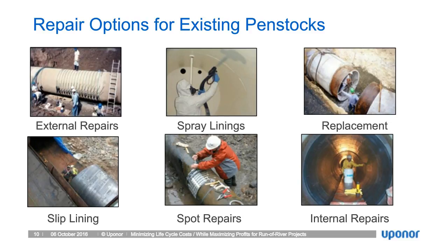Spray linings: sometimes if it's a steel pipe and you're just looking to reduce corrosion potential, or some of the linings have a better Manning's number, they're slippier. Linings such as epoxy or urethane can be applied to the surface to help extend the life expectancy of the materials, as well as increase flow velocities because the liners typically have less resistance. The con with liners is that they are liners and they do wear out. If you're carrying any sand or abrasive material that's going to wear them down, you're going to lose that advantage and re-expose the steel or other materials.